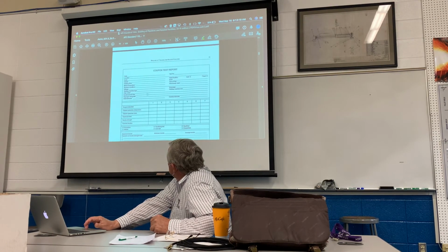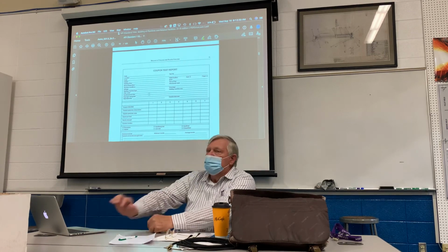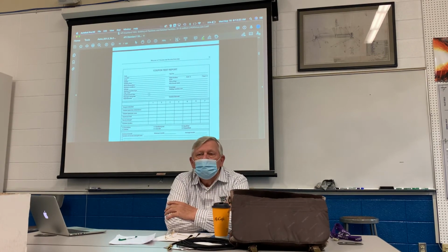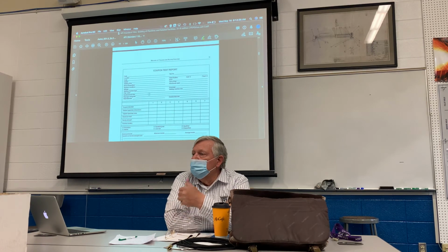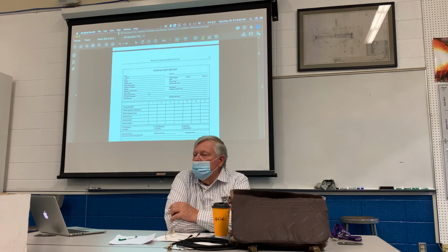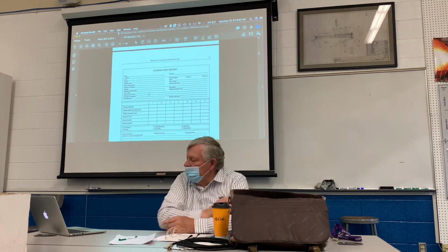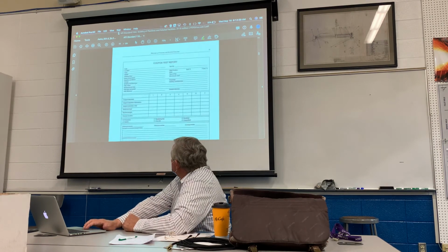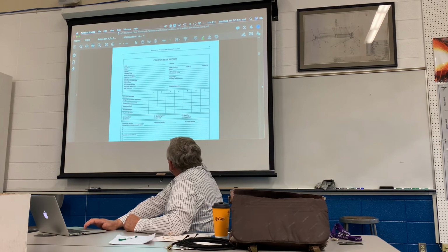If the reinforcement size is 3/32 of an inch, did he pass the test? That's a visual flaw, he's made the weld too big. There's too much reinforcement. Why is too much reinforcement bad? Stress riser. Stress riser, yes. Extra stress. Anyway, that one's easily fixed.